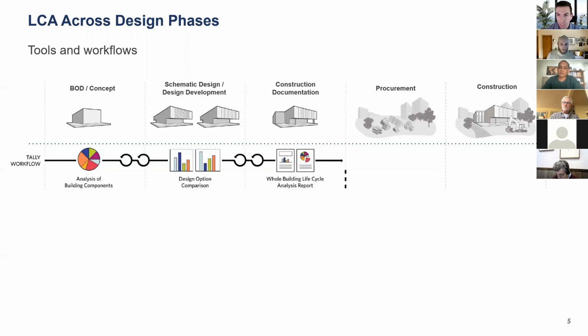In terms of the LCA tools that are aimed at the different users, for a designer, there are a number of tools. Right now I'm showing Tally, but that's just one example of multiple tools that I'll also touch on in just a bit. They're available out there. But basically, how you can use these tools in the different design phases is at the concept stage. You can really look at: is it better to create a new building or retrofit an existing building?